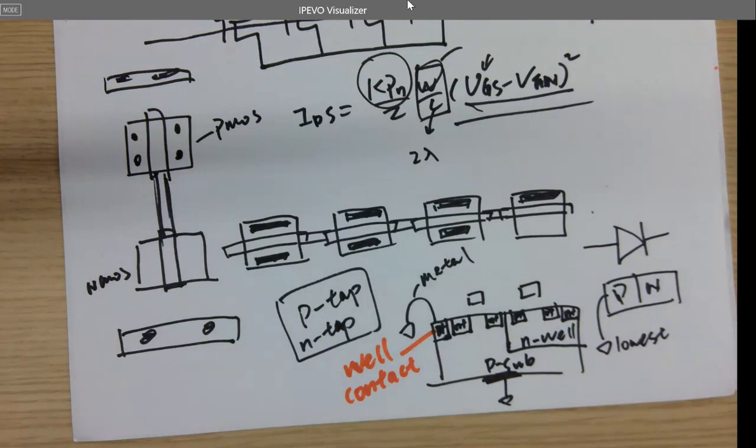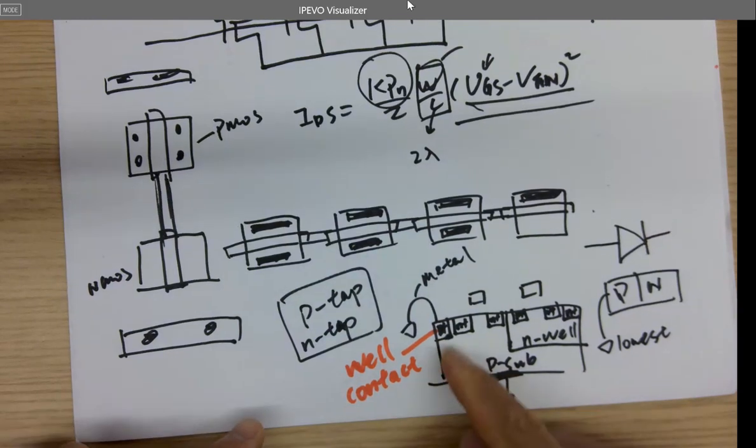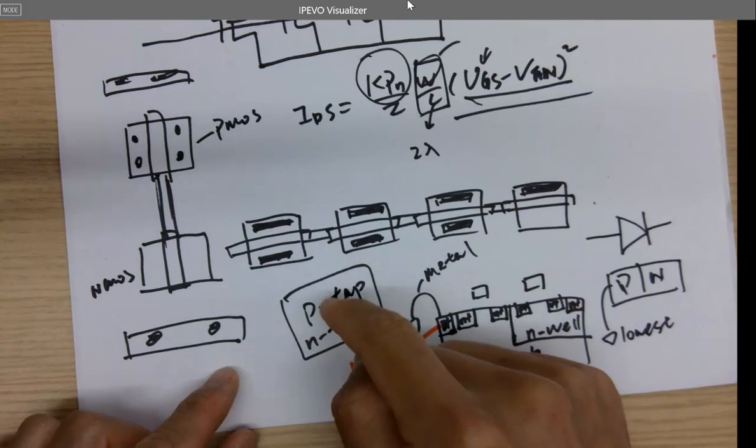You have hundreds of components in the library. If you are manually pulling them from the library into your design, you have to type the name in and press enter. You get frustrated. You put a P contact, enter, nothing. So you start blaming this technology, they didn't even put a well contact in there, but actually they have a different name.